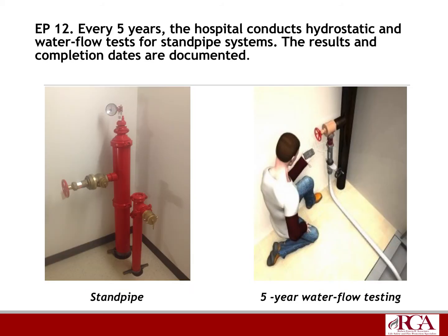EP12, every 5 years, the hospital conducts hydrostatic and water flow tests for standpipe systems. The results and completion dates are documented. So a standpipe, the best analogy I can provide is that a standpipe is to a building what a fire hydrant is to a city block.